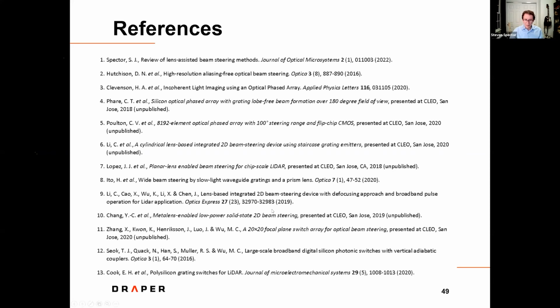Oh, yeah. I assume we're talking about our MEMS switch, and it is very much a single polarization device. I'll make no bones about it. The waveguides are typically single polarization. You might be able to force the other polarization down the waveguides, but then you need a different kind of grating, and you really couldn't.